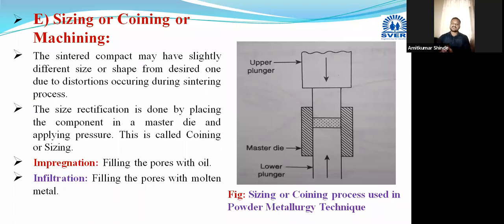After impregnation or infiltration, we cannot go for sizing or machining operations. Any size rectification must be done previously, and then you go for impregnation or infiltration.